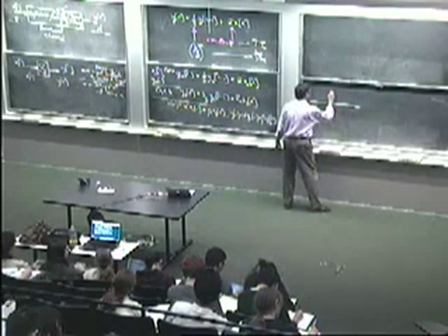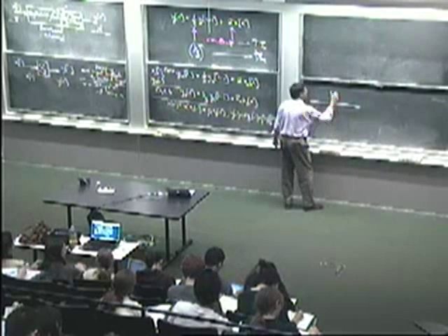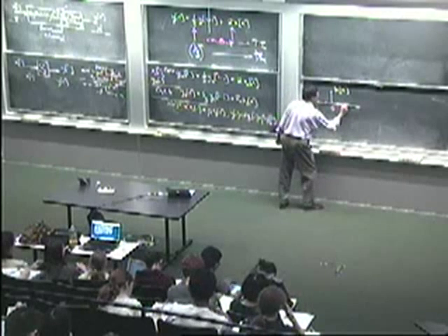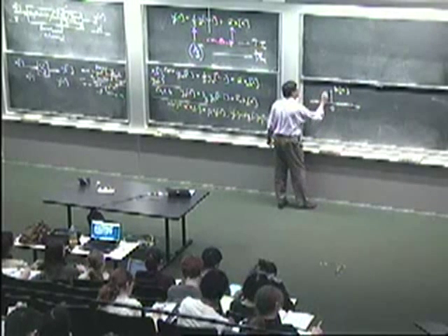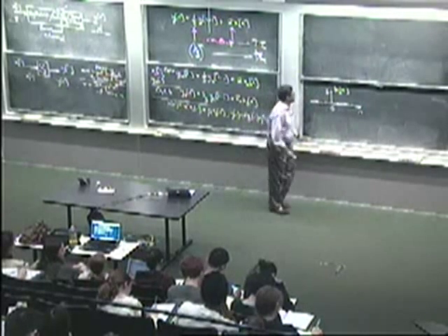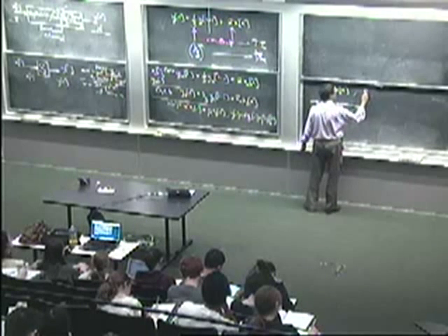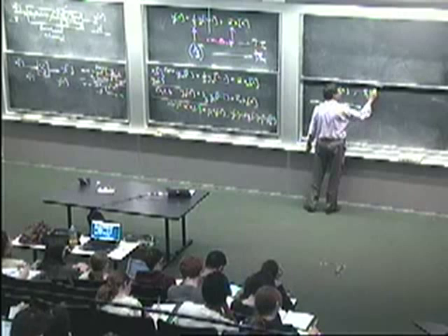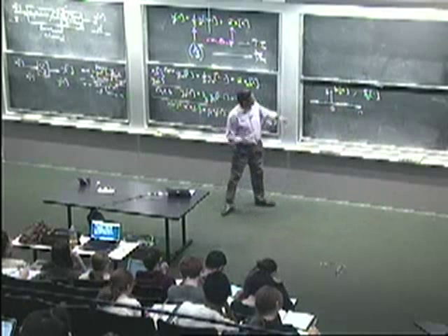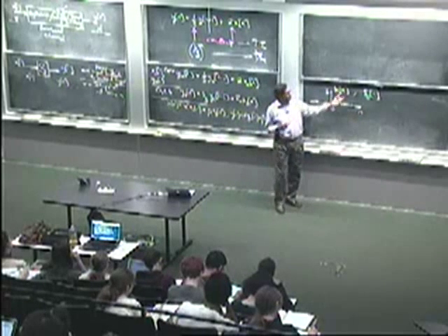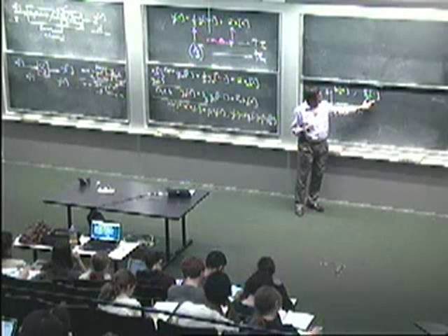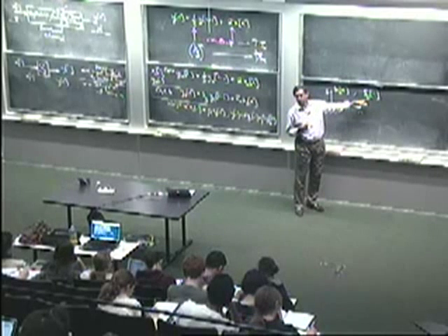So the unit sample, this is a signal delta n, which is an entire signal. It's not just the number 1 at time 0, it's the entire signal. Okay, that's the unit sample function. There's another notation that's also sometimes used, which is delta sub 0 and dot. So this notation is a little bit more evocative of a function, whereas here you are often tempted to think of it as a number. This says what I'm looking at is a function. It's a unit sample function, and the 1 is at the value 0.